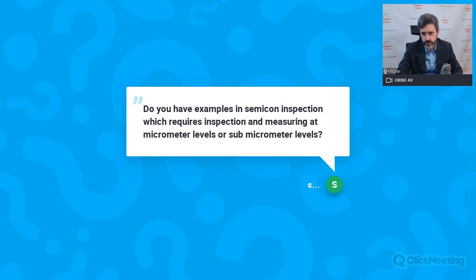Having said that, we have tools which provide very good sub-pixel precision. In some applications, you can measure with 1/10 of pixel, but it's very easy to make misinterpretation, because with those very high precision tools, I know we are sometimes compared to laboratory equipment, and when you go to production, there are all sorts of trouble: unequal edges of objects, texture, or even grease on metal surfaces, which reduce the possibility to make very high precision measurements a lot.